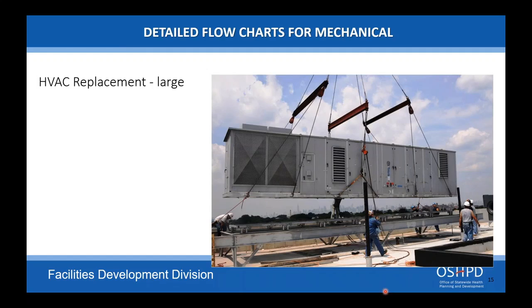The scope of work is going to be exactly that. You're pulling the old one off and adding a new one. There may be minor alterations required due to duct relocations to align with the new unit. A lot of these units are custom and they can work with the existing openings. But this is your scope of work. You do not have to take anything downstream to the ducts, to the dampers, to the rooms, etc.